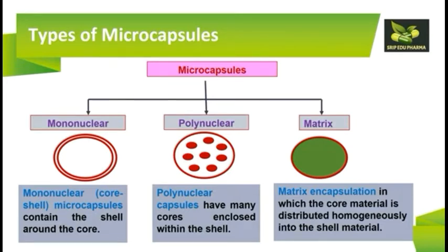So the third one is pan coating. This pan coating is extensively employed for the preparation of controlled release. In pan coating, the coating is applied as a solution or atomized spray, and the solvent is removed by passing warm air over the coated surface.